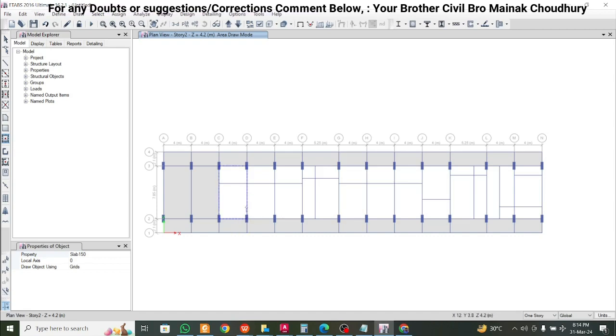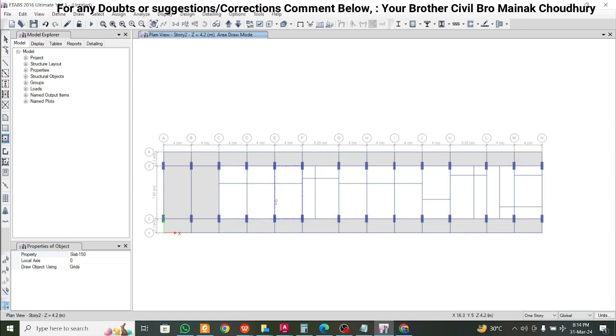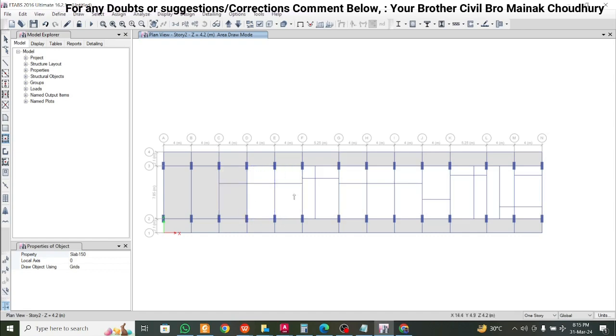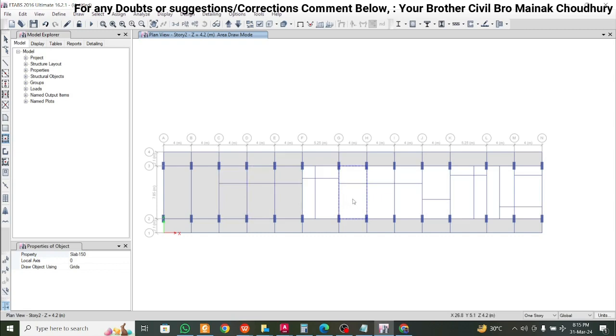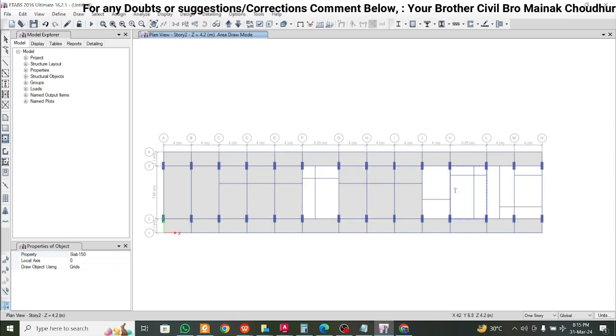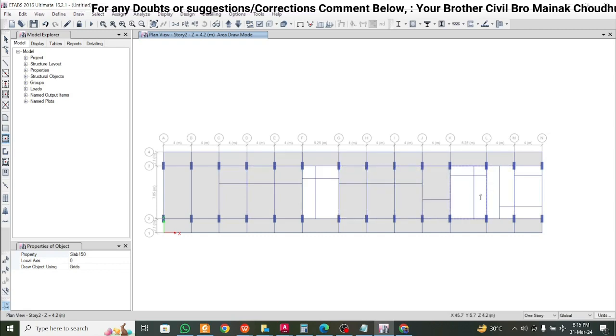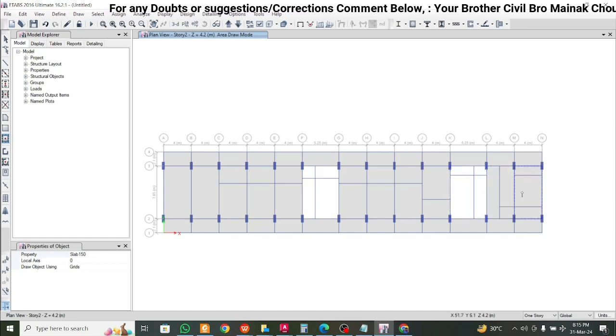Do we want to divide this slab or treat this as a single slab? Let's treat this as a single slab. If you divide this slab, then you have to take the rectangular area option. I think this way it is better. Treat this as a single slab. Ignore the secondary beams, though they will provide some support here. Okay. Yes. Let's move on to the next part.